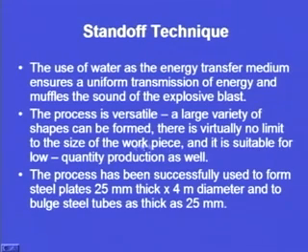There is virtually no limit to the size of the workpiece. Already we have seen that size is no limitation in high energy rate forming processes. So, we can make big sizes and big shapes also, and it is suitable for low quantity production as well. Most of the time we say that the production rate and the volume of production should be high in order to justify the cost of the infrastructure or the cost of the machine, but here this can be used for low quantity production as well.